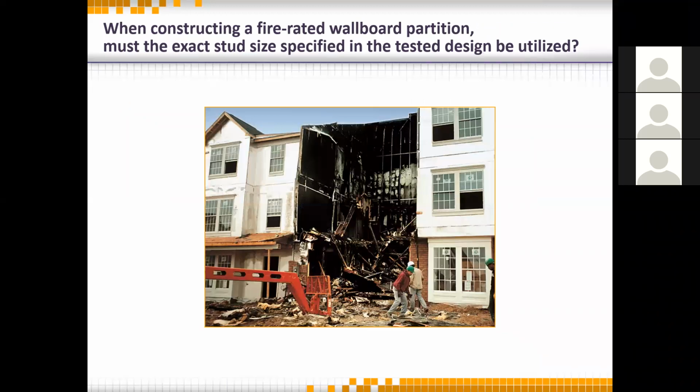Before I answer the question, real quick, some of us are in markets where we do area separation wall. Although the picture's not pretty, it's a success story for the area separation wall. We had a fire, obviously, in this particular building. The area separation wall is a self-supported metal stud system with 2 inches thick of drywall. So 2 layers of 1 inch thick shaft liner.